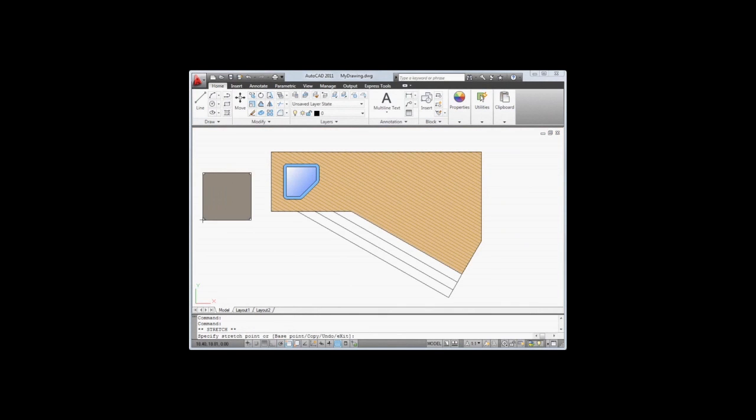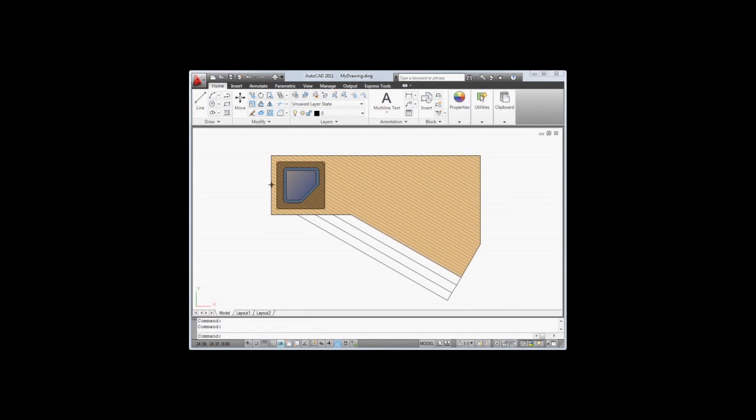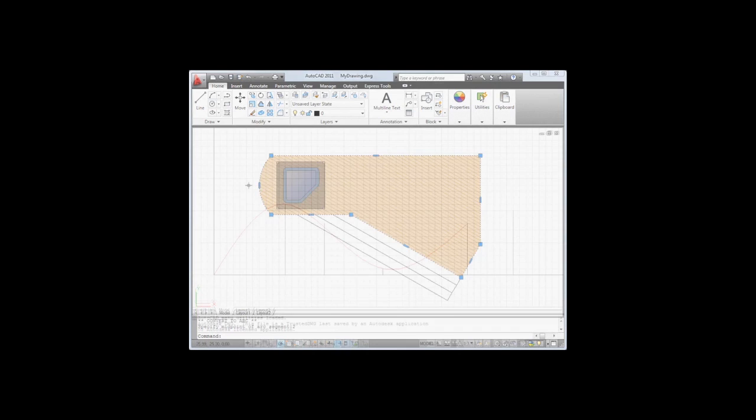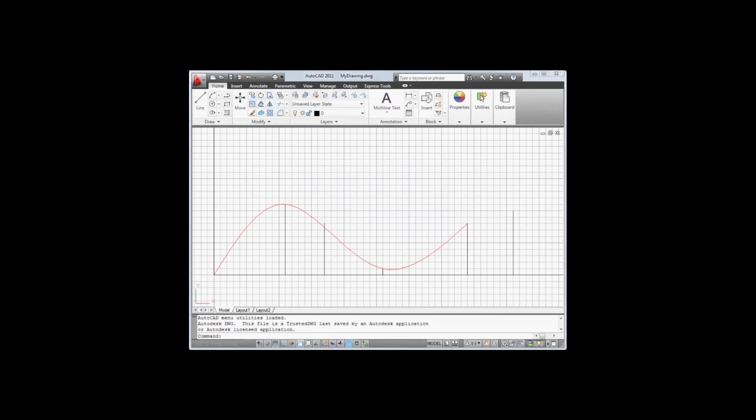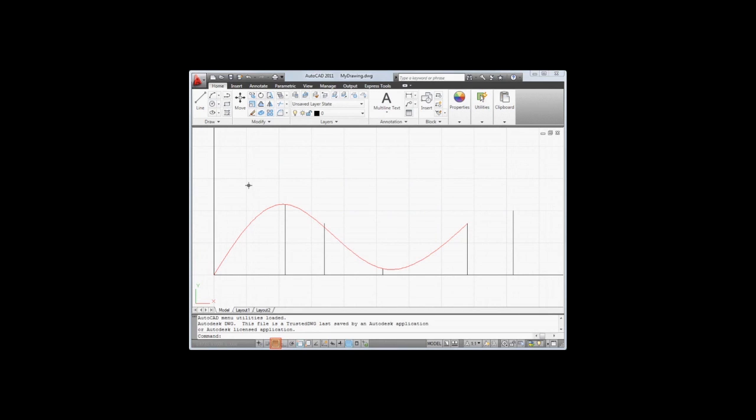We've introduced a new property, transparency, that you can set for layers, objects and blocks, just like you would set the color property. Polylines now display multifunction grips with dynamic menus that you can use to quickly make changes to segments or vertices. You'll notice that we've redesigned the grid to look like graph paper. You can change the color of the grid lines, and as before, you can turn the grid on or off.